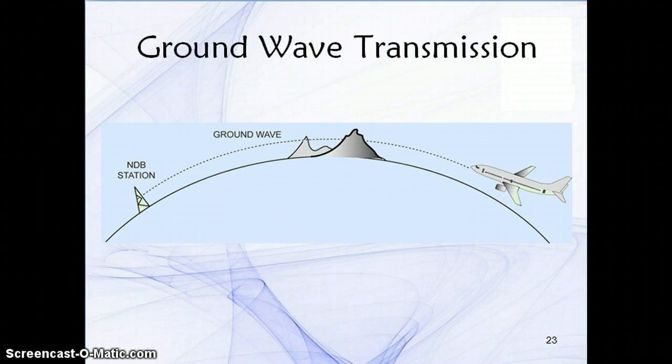In mountainous regions, they flow through and around the obstructions. They produce steady communications and navigation because the signals are not blocked by the horizon. They have many limitations, though, including great susceptibility to electrical interference, natural and man-made. There are few channels and a lack of global range. The services now on low frequencies are ADF, Automatic Direction Finder, LORAN, and until recently Omega, which has been decommissioned because it was much too expensive to run.